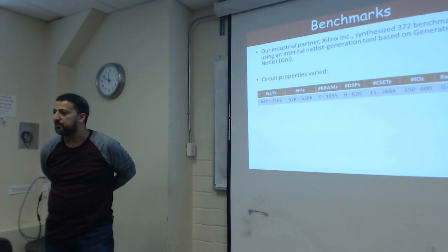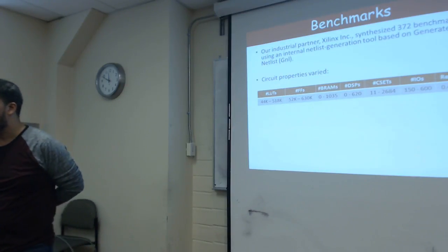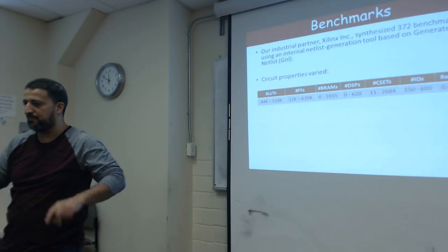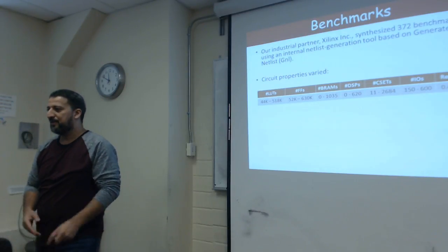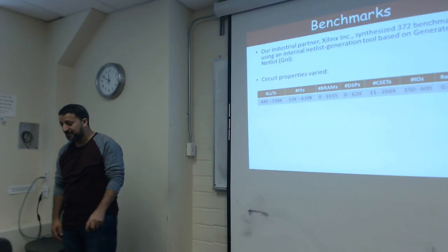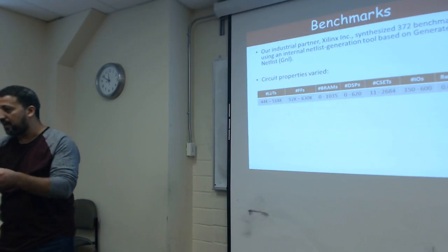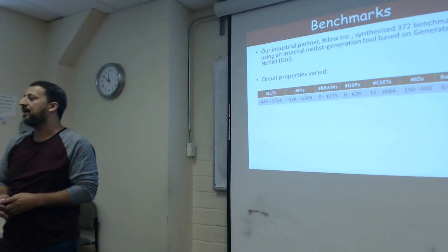Just one quick question. It must be happening somewhere, but let's say you have many cases of a LUT directly driving the flip flop, and you have to pack those side by side. So doesn't that create situations where you'll have a LUT and it directly drives the flip flop, but the flip flop is not in the adjacent part of the slice, meaning within the slice? Yeah. Within the slice, yeah.